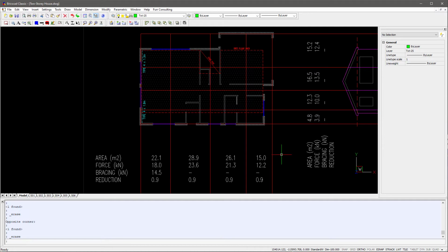There's a few ways we can deal with this. We could use a steel brace frame, which is one of our last resorts for bracing. We could try and readjust our bracing areas, or we could justify the transfer of forces to other brace walls in the lower floor. Given we aren't dealing with a substantial amount of load, trying to transfer the load elsewhere is probably a good option.